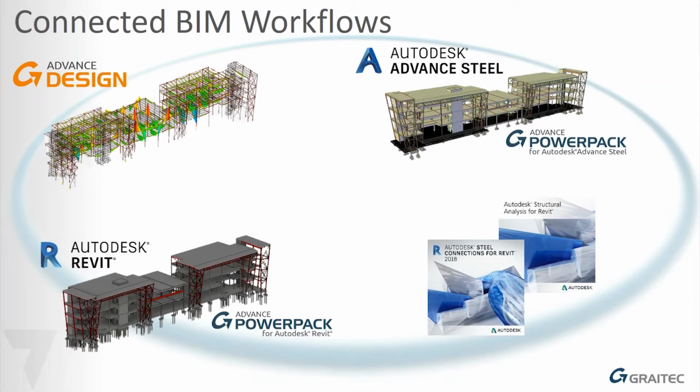So to quickly start with a very brief two-page PowerPoint, what we're going to look at today is how we can start to introduce connected BIM workflows, particularly within the structural discipline. We're going to heavily focus within the Revit environment, and connect a Revit model out to a Graitec product called Advanced Design for FEM steel analysis.